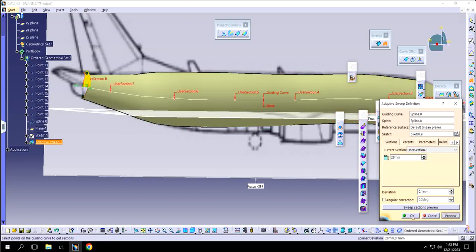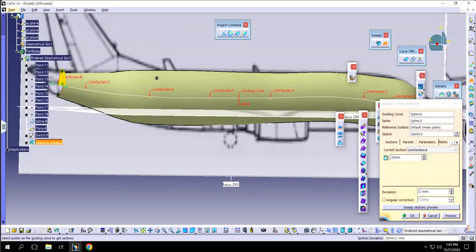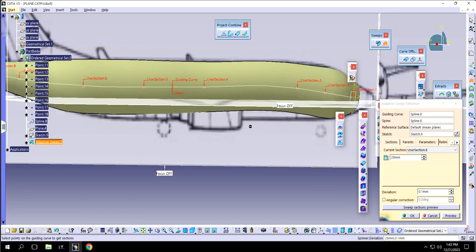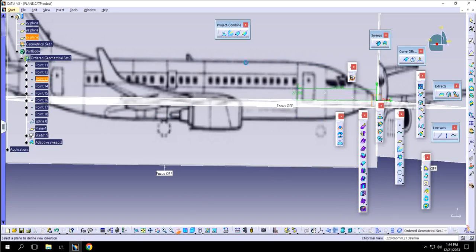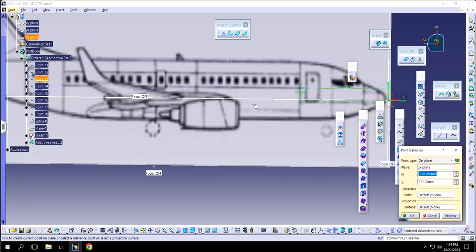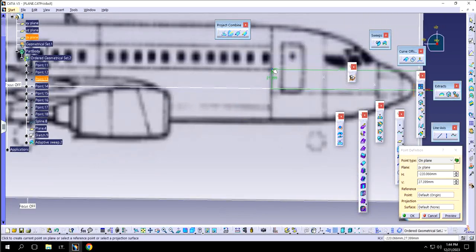Yeah, looks close enough. So similarly now the thing is, although we have tried, you can see that the upper surface appears to be very close, but the lower one on a few of the points is nowhere closer to where we want it. So how to adjust that is by using the points at the right location. It means that your points were not very close to the center of the actual fuselage. You can just play with the point position. If you want to play it manually, it's your choice, or if you, so these are already defined, so you can play with this as well.